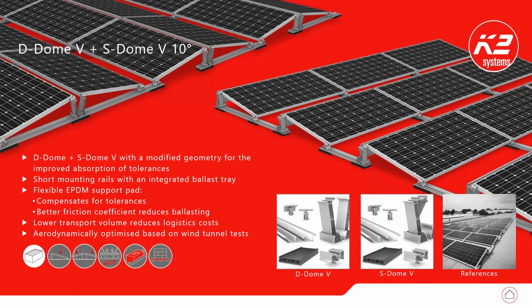One huge advantage and main feature of this new system is the flexible EPDM support pad, which compensates tolerances and movements. So all the forces, probably wind force, that are attacking the PV modules will not be transferred into the roof itself. This flexible EPDM pad compensates all movements that are happening on the PV panel. At the same time, it also has a better friction coefficient.